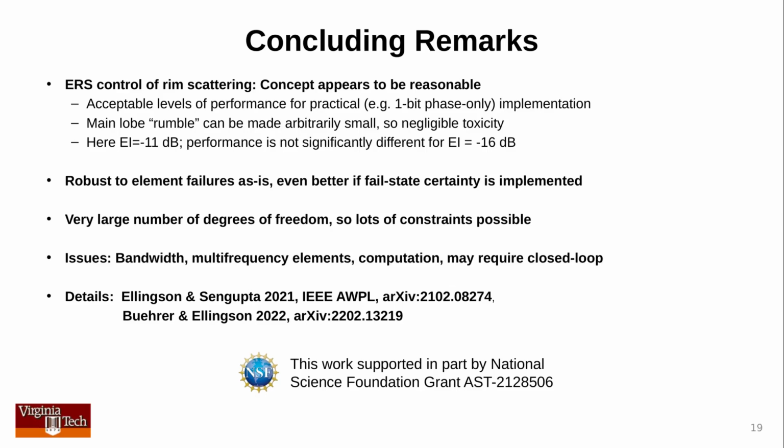Of course, I should also mention items of concern that remain about this technology. As I showed, bandwidth is perhaps okay, but nevertheless small if you do nothing to address it. What I did not mention is the multi-frequency problem. For example, if you use this dish at both L-band and X-band, and you want to be able to steer nulls at both frequencies, well then you need elements that can support that. So there's a non-trivial problem in reflector array design remaining to be addressed.